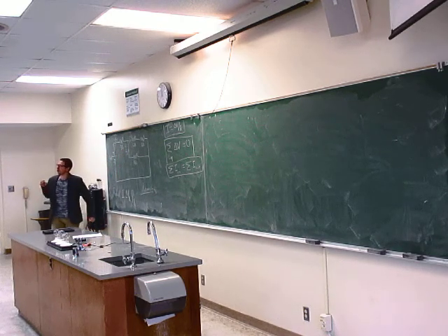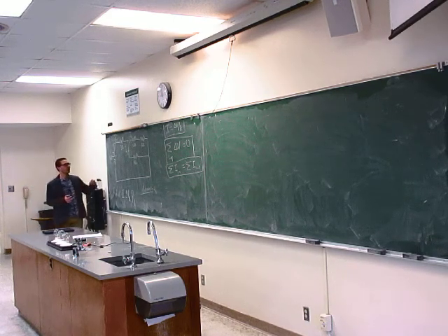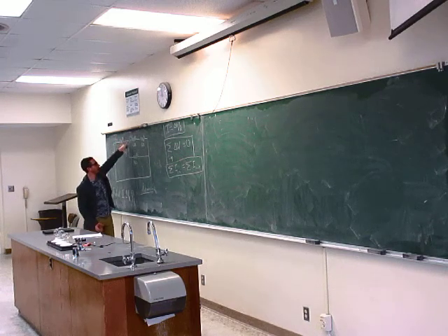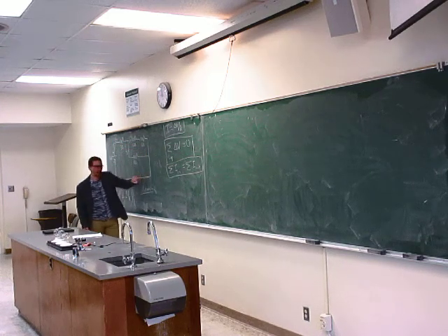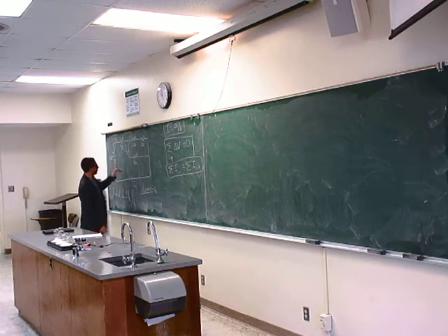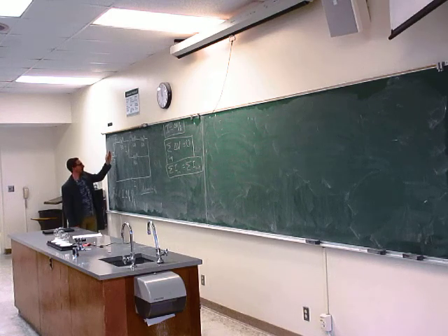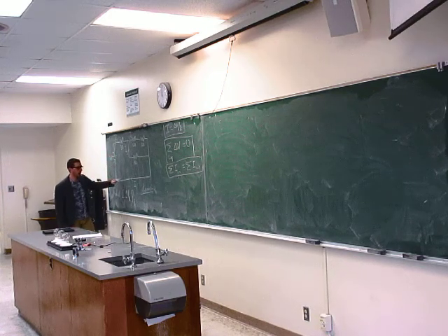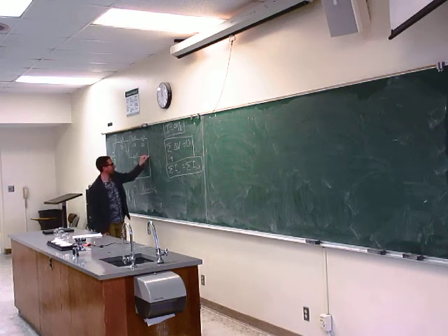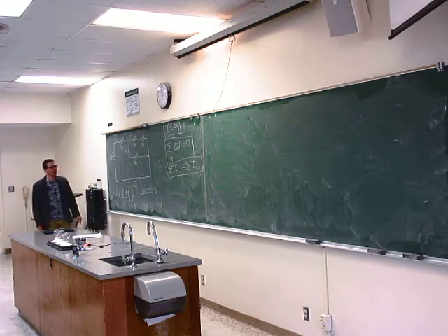Remember, resistors don't use up current, they dissipate electric energy. So charge is never used up, charge is conserved. So if it splits into I2 and I3 here, it has to pinch back into I1 here. So down here, it's also equal to I1. Which you can also see just by tracing this backwards. If I1 is coming out this way, it has to be I1 all the way from this junction point right here.